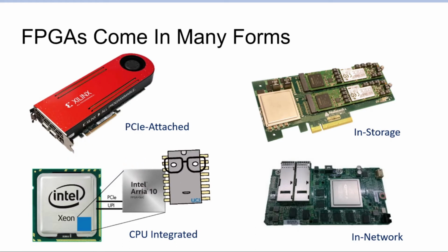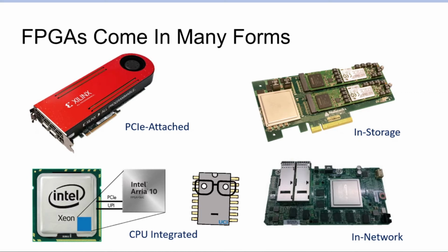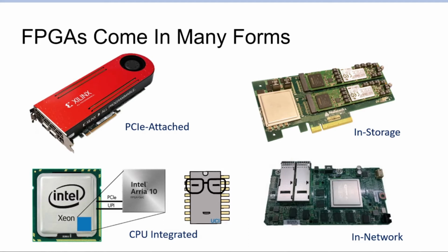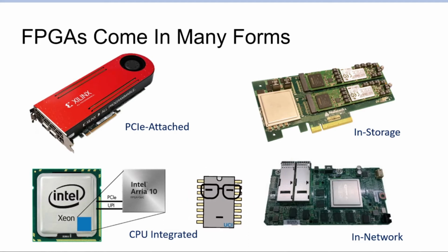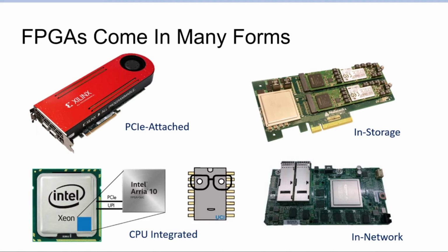And there are also patents and known projects in which Intel and AMD both are aiming to put small pieces of FPGA fabric on the processors themselves and have them communicate either by cache coherent communications like the one you see here, or by an instruction extension sort of approach, kind of like how with AVX-512 there are mentions of provisions for using that 512-bit interface to communicate with custom designed FPGA implementations of custom designed instructions.